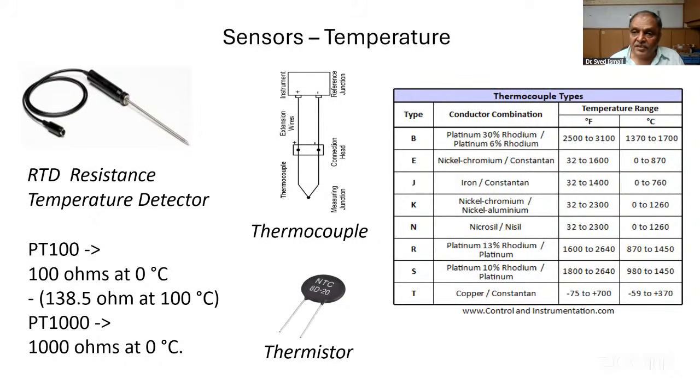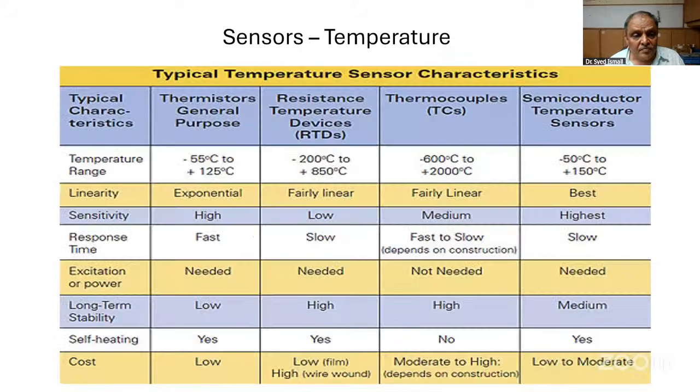But for very high temperatures, use a thermocouple. A thermocouple is not very accurate, but it goes to a high temperature range. The temperature range is very wide, from minus to plus we can go. And it requires a little bit of skill to decide which type to use. This actually uses the principle of two metals joined together and put in heat; whatever heat or cold, it will generate that much electricity. That is the principle of thermocouples. So these three, you must refresh.